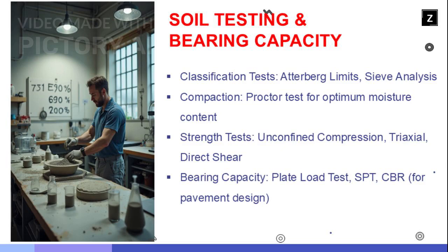Soil investigation determines the type and strength of foundation. Key classification tests: Atterberg limits, plasticity index of clays; sieve analysis, grain size distribution. Compaction testing like the Proctor test identifies the optimum moisture for max density. Strength tests: unconfined compression for cohesive soils; triaxial and direct shear give friction and cohesion values. Bearing capacity is assessed using plate load test, actual foundation simulation; SPT, standard penetration test; CBR, California bearing ratio for pavements.